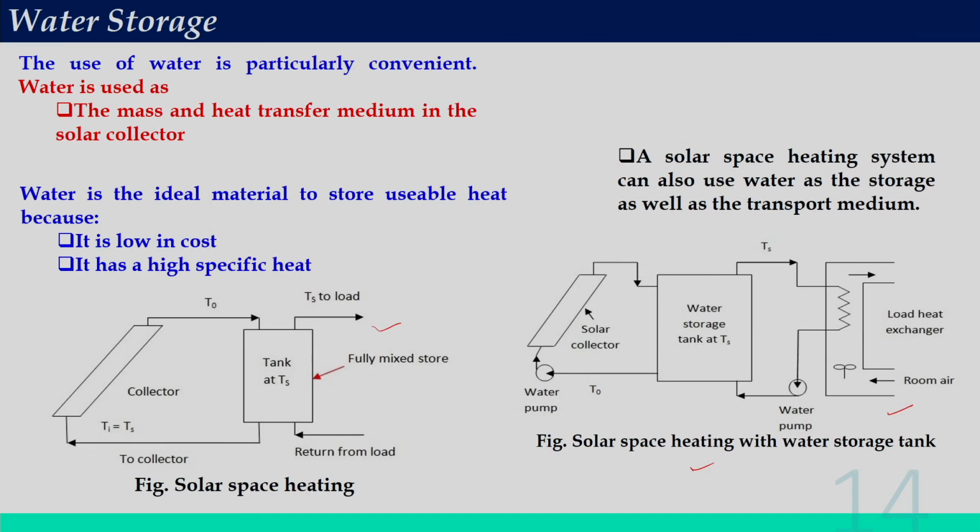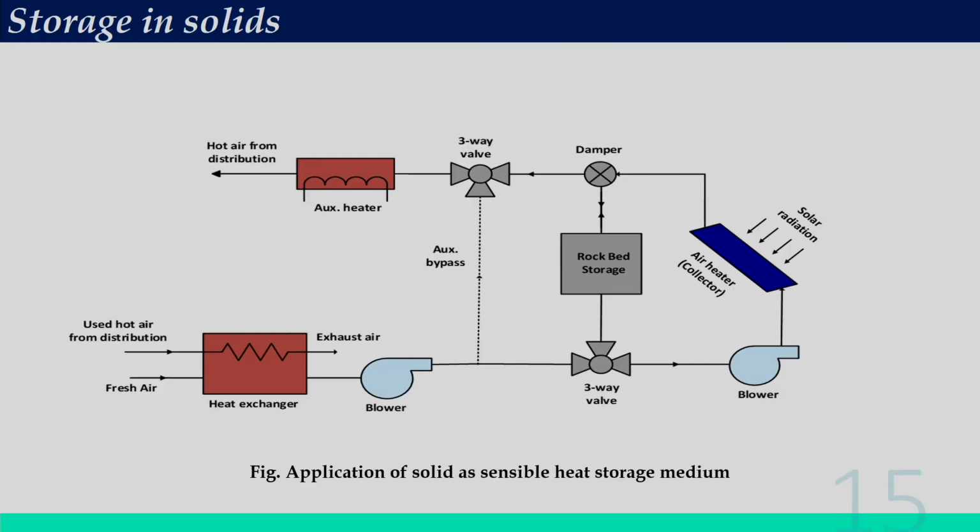Okay. This collector is a liquid flat plate collector. Sometimes we will discuss a solar air heater, where air is introduced, heated, and then stored in a pebble bed, which can be applied for other applications. So, here this is a solar air heater where air is heated and stored in a rock bed storage, and whenever required it can be used based on the applications.